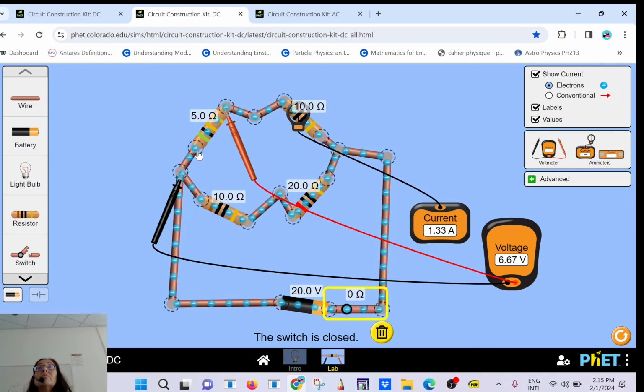You have an AC generator here. You move a magnet inside the coil, and that's how AC is produced. Any question? Again, this is the peak value, so here we have 170 volt. This is what we call the RMS. It's some kind of average, and that's what you will be measuring with a voltmeter.